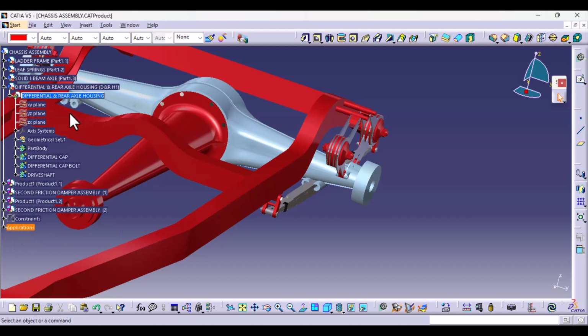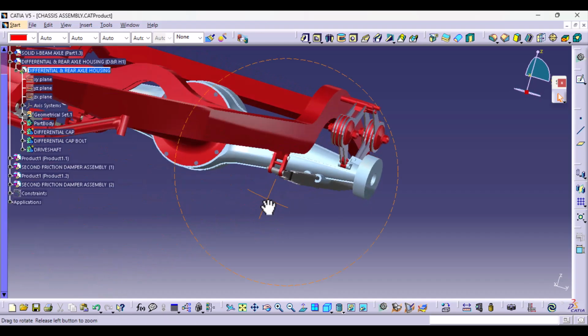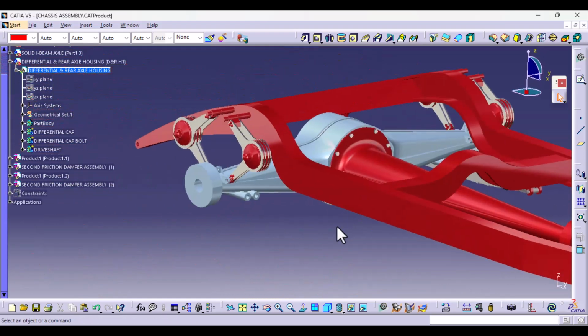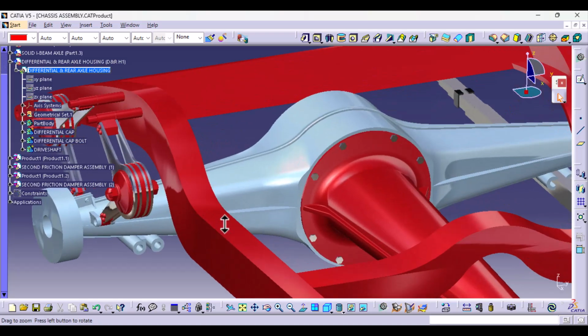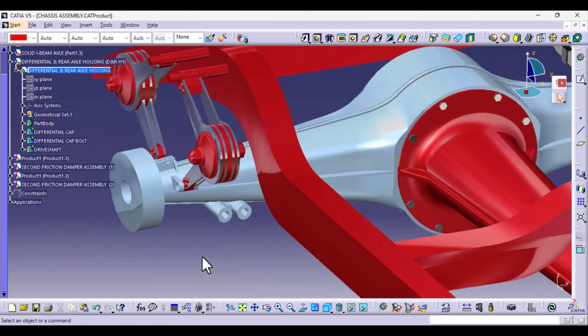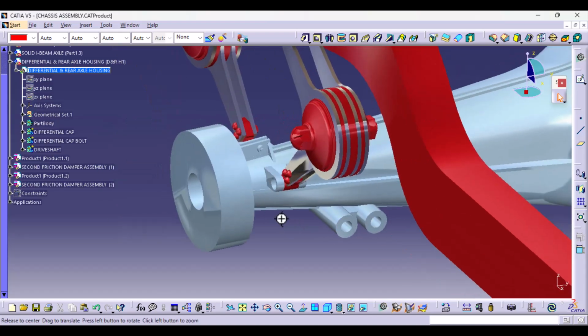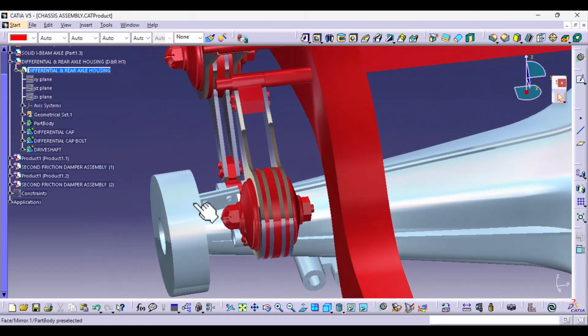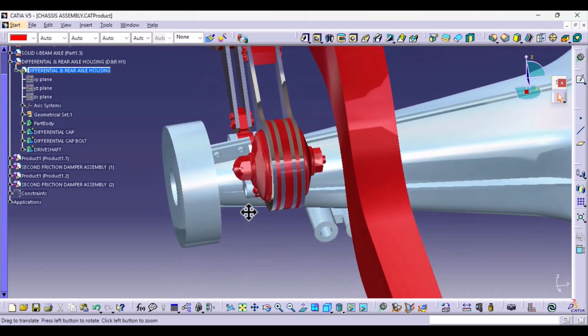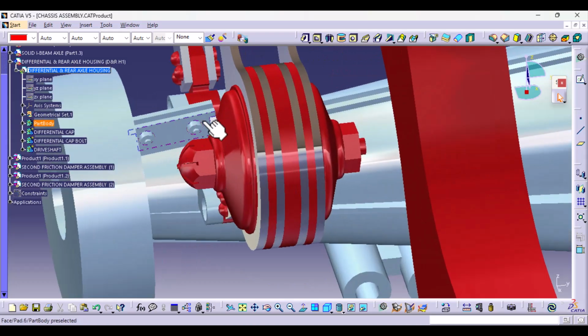blueprints for now. When you're making adjustments to an upstream component, you want to make sure that the subsequent parts that you created afterwards are properly constrained such that they will move together with the part. For example, if I reduce this distance and this width, if I scale it down, I don't want this attachment, this part that we created here, to remain in its position.